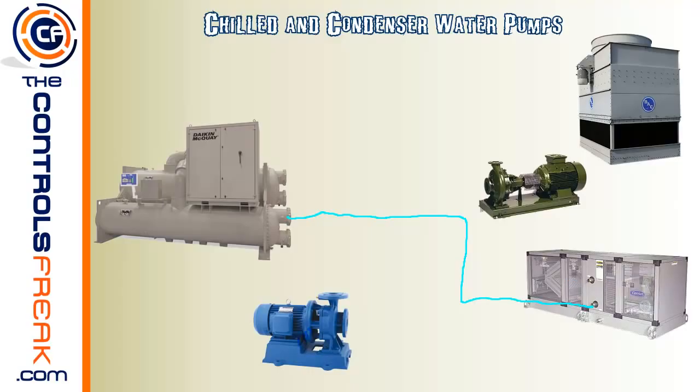Now we want to draw the water coming back out of the coil that's ready to go back to the central plant and get cooled down again. So that'll be this darker color here. And we'll send it this direction. And I'm sorry, pipes don't normally go on a diagonal slant like that, I promise. But it comes into the inlet of the pump. And in case you're not familiar with pumps, if you looked at this type of pump here, the inlet is actually going to be this horizontal part here. And there's an impeller in here, so you can imagine it like a boat propeller, but this is an impeller, which will draw the water into the center portion of it and then spin it around and shoot it out the top here. And this is going to go right back inside to the chiller.